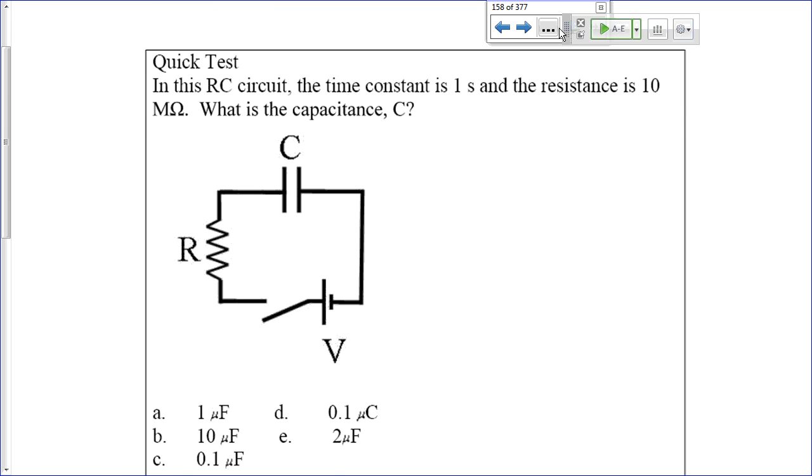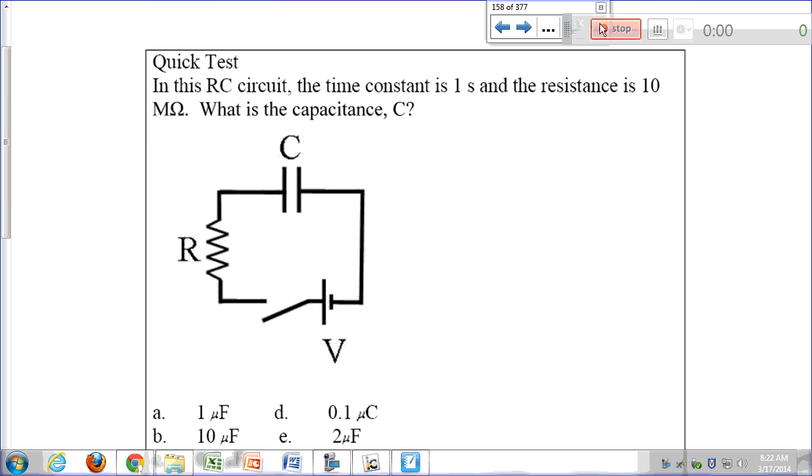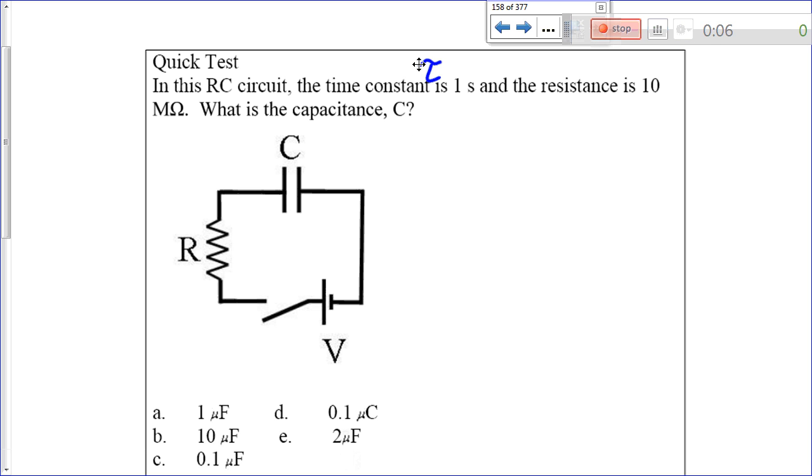That's where I was talking. Like, you say 1 second, but should we treat it as 10? No, the time constant is 1 second here. That's tau. It's equal to 1 second. So we don't need to treat it as equal to 10. The only thing is, this capacitor requires 10 seconds to fully charge and 10 seconds to fully discharge, given this circuit with this resistor.